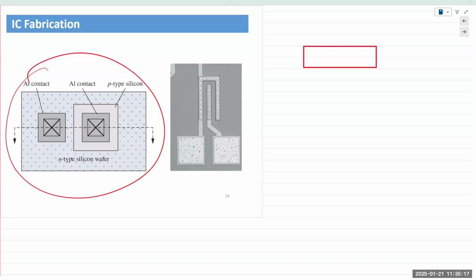So I wanted to show you, this is an actual silicon wafer. I'm gonna pass these around. These are brittle. If I drop them from a height of like 1 inch, right here, if it just falls at a slight angle, it's gonna shatter and break. Okay, so you don't even want to wave it like a fan. If I do that, the wind is gonna break and shatter these. So these are extremely fragile.